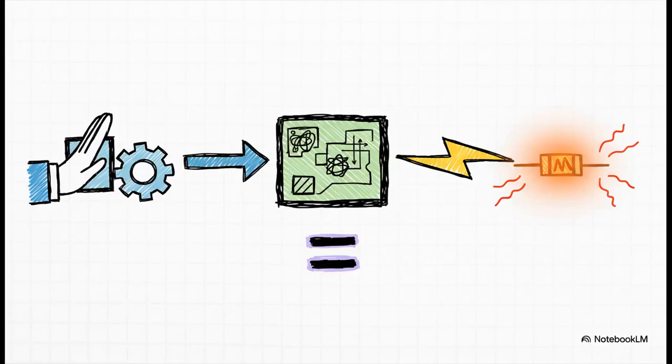And that leads us to this amazing conclusion. If you calculate the mechanical power you're putting in, which is your pushing force times the velocity, it turns out to be exactly equal to the electrical power being dissipated as heat in the resistor. It's perfect energy conservation. The work you do pushing the rod is perfectly converted into electrical energy and then into heat. Nothing is created or destroyed.